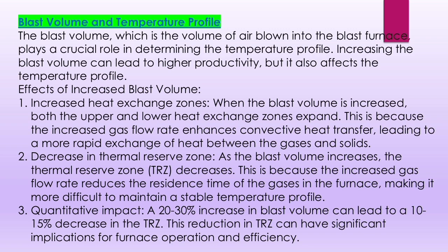Blast volume and temperature profile. The blast volume, which is the volume of air blown into the blast furnace, plays a crucial role in determining the temperature profile. Increasing the blast volume can lead to higher productivity, but it also affects the temperature profile. Effects of increased blast volume. 1. Increased heat exchange zones.